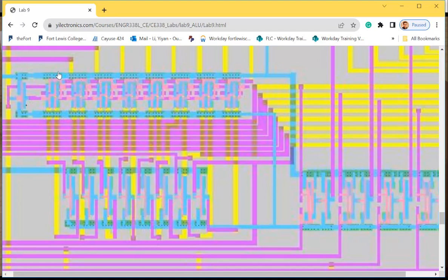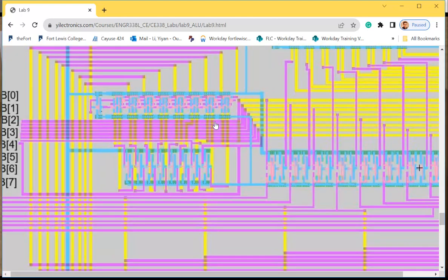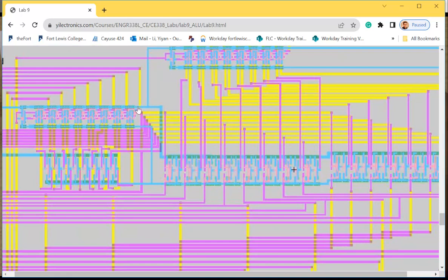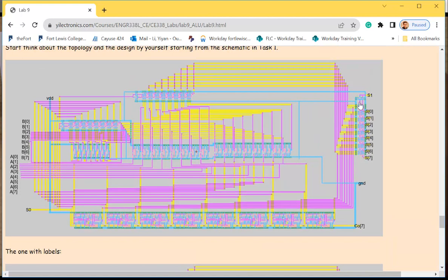For the groups of transistors that are for one functionality, probably one component in the circuit, you definitely put them in the same well. But you have another group of transistors over here at a super long distance, so you don't always have to do that. Just keep the transistors for the functionality of that component in the same well. It's impossible to keep, for example, the PMOS here and the PMOS there in the same well. How to do that? You connect them through the metal instead of a piece of pure well. Okay.